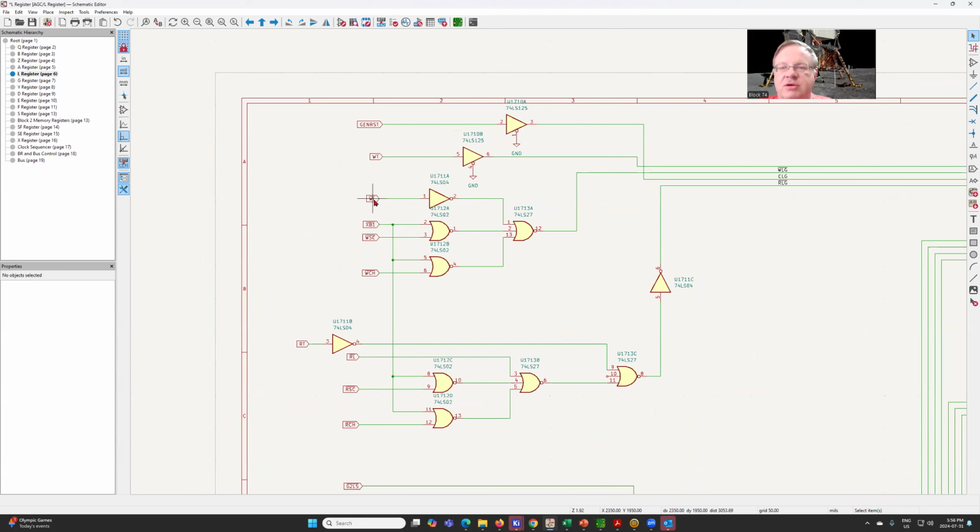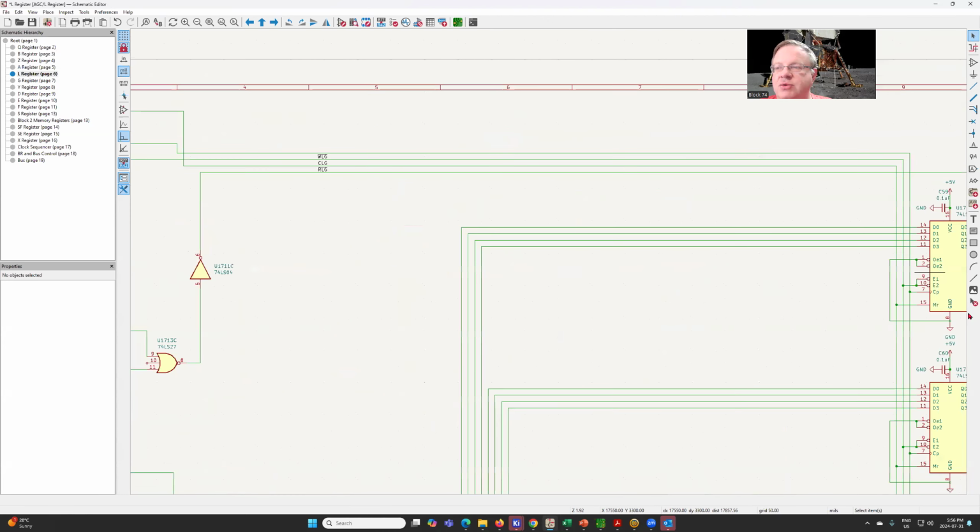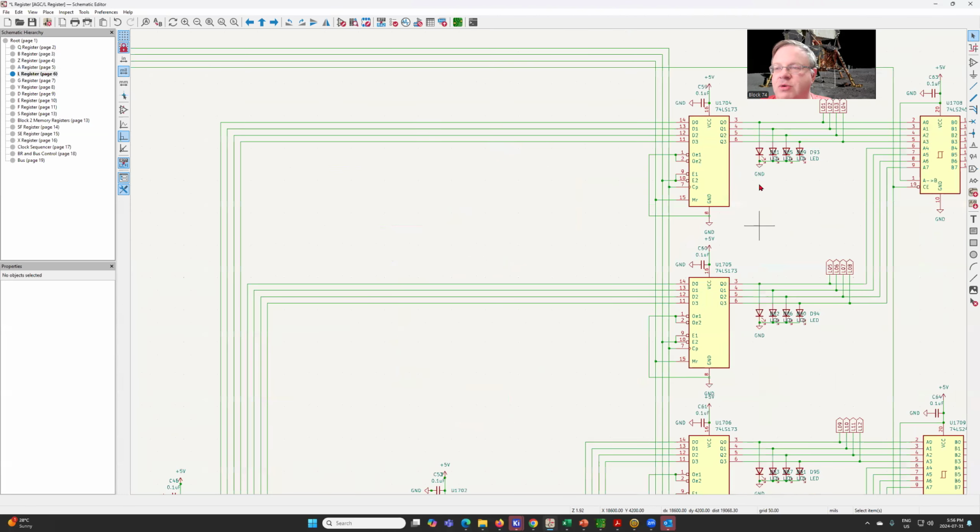So we can generate our write line control, or basically the control pulse to write data into the L register, from either the WL pulse, or the memory address 1 with a WSC, if we're writing it in as a special directly addressable register, or WCH if we're writing it in as a channel register. And then this will generate our control pulse in order to write data into our L register.